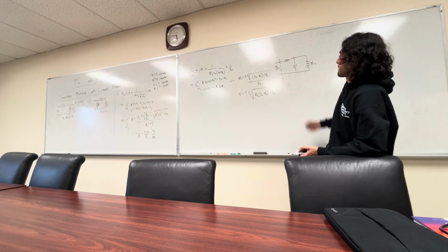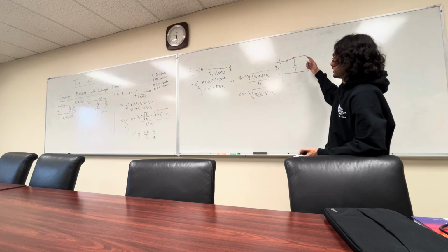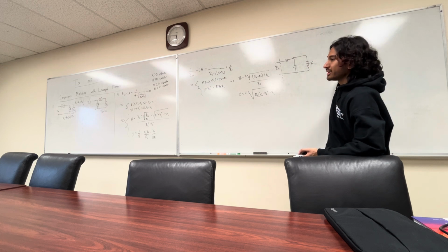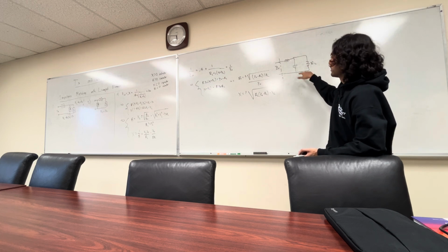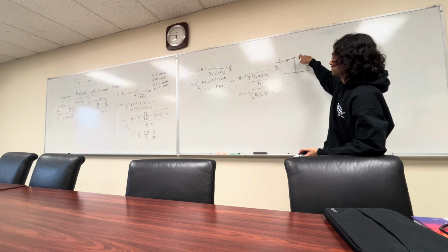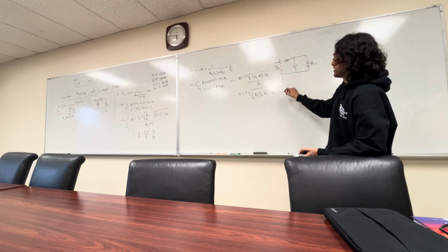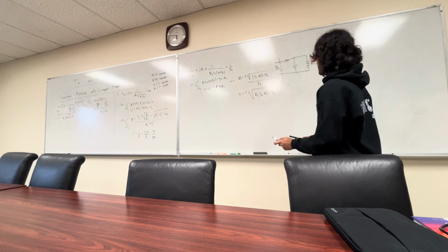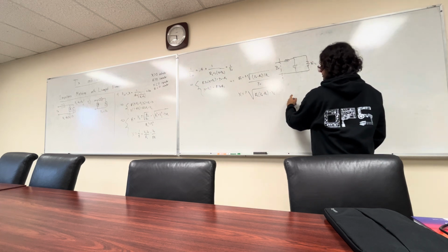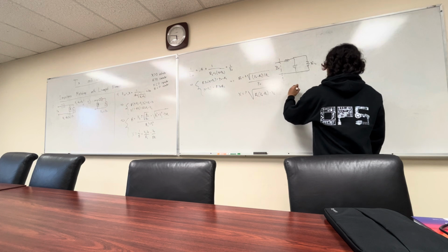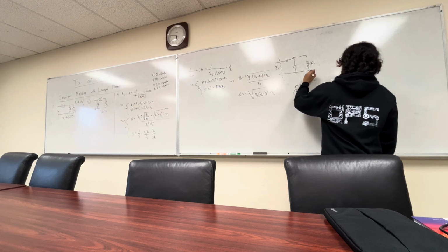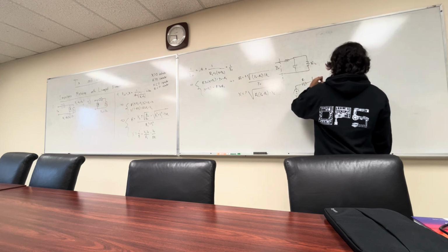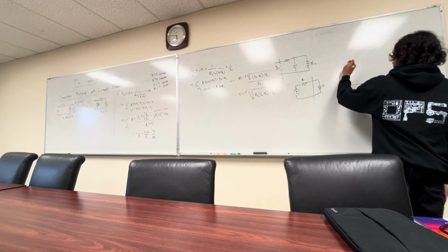Ideally here, your signal will be slightly attenuated at these frequencies, but it's going to go through more or less unimpeded and impedance matched. As you stray away from these frequencies, you don't have conjugate matching anymore. And if you remember from circuits, you get something that looks like this. Maximum power transfer occurs when these two R's are equal.